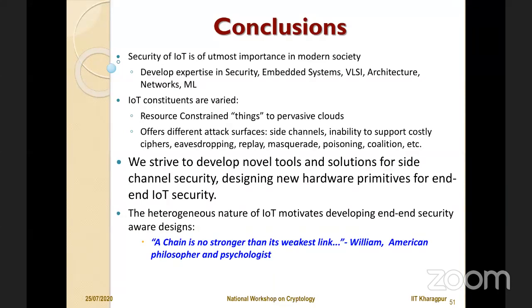I would also like to mention the fault attack, which I have been working on for a sufficient amount of time. It is interesting to see that people are now able to do fault attacks which work on servers also. For example, there is a famous bug called the Rowhammer bug, which works even on computing systems, where they can fault a DDR or DRAM chip to create faults. There is a recent paper which shows how a fault attack can work on GPU machines as well.